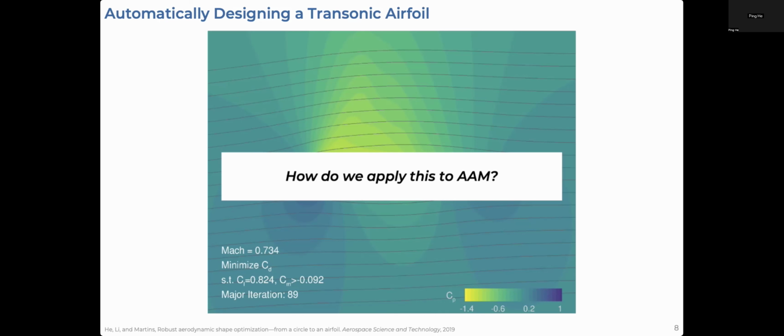Now, for the methods we use, for the propeller aerodynamic modeling, we use blade element momentum theory in a tool that we developed in-house called Helix. And for the wing aerodynamic model, we use RANS CFD within DAFoam.